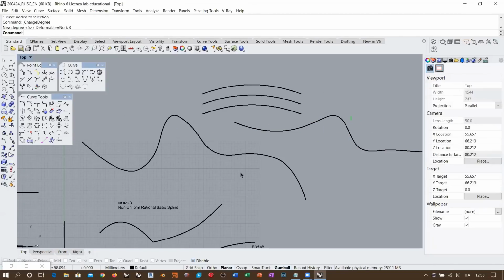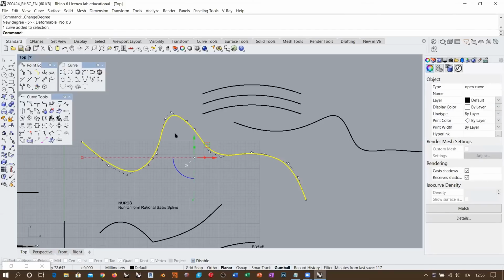So when you want to change the degree of a curve, take into account that if you change the degree by increasing the value, you have no deformation. You are creating a more complex topology, but there is no deformation for the curve. Okay. So you can increase the degree, basically I would do this between degree 2 and degree 3. I wouldn't do this with a higher degree curve, for example, from 3 to 5. Remember to skip even numbers, okay? So from 3 to 5, I wouldn't do this because we get the result that we got here, okay?